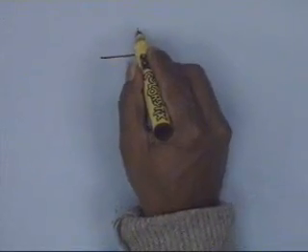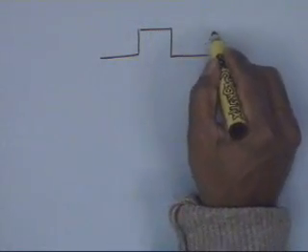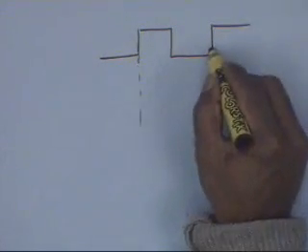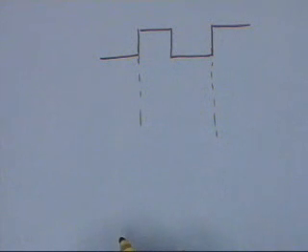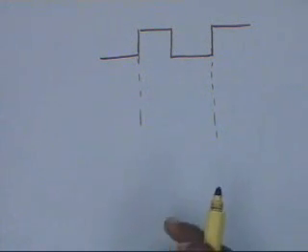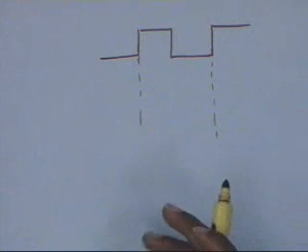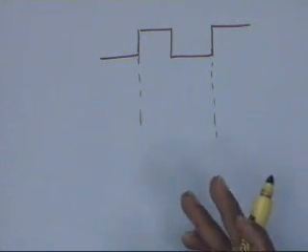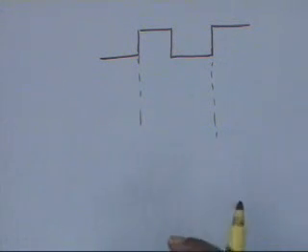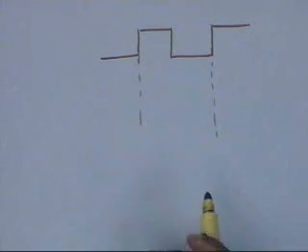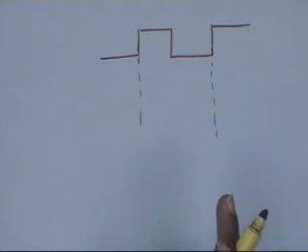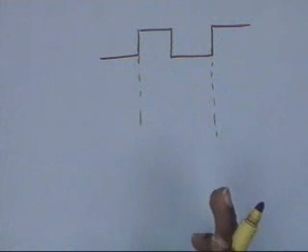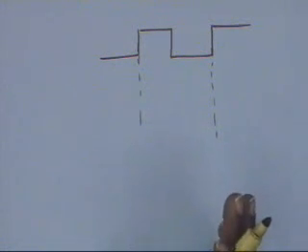One method is, unlike other control signals, almost all other control signals can directly come as an output in case of a Moore machine as a decoding of a state, in case of a Mealy machine as an output which decodes the state and the input signal. But for the write signal, if you want to do a write operation in one clock cycle, you will almost always require some more logic.